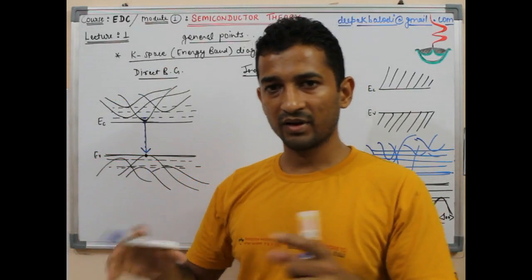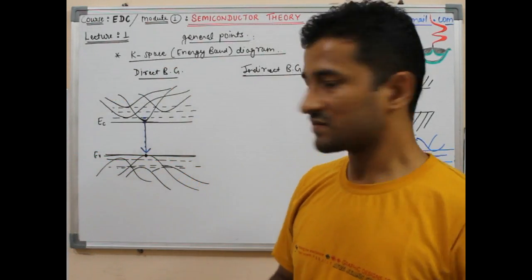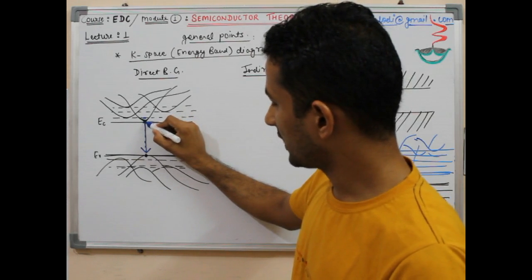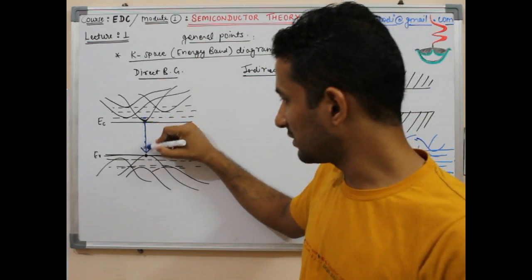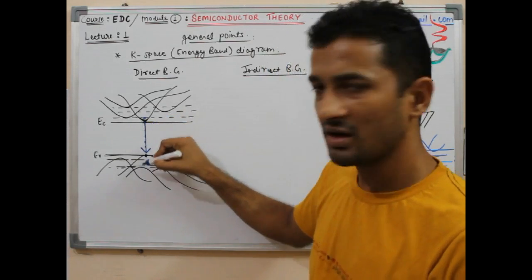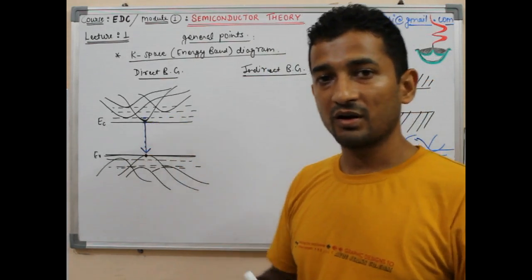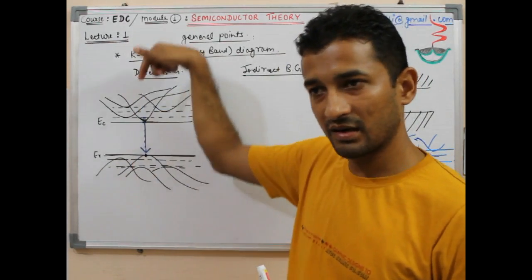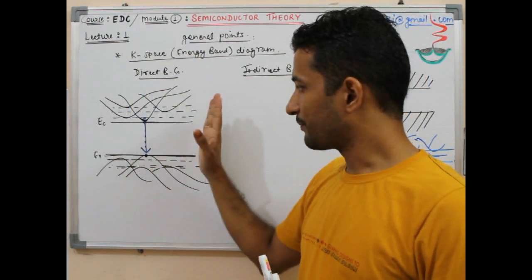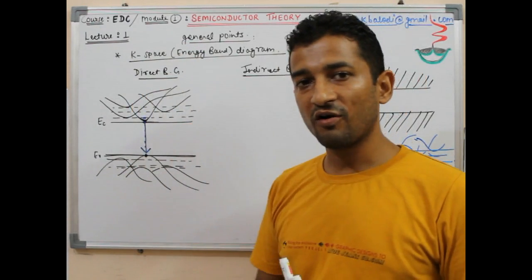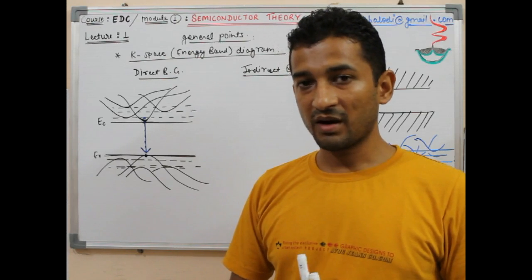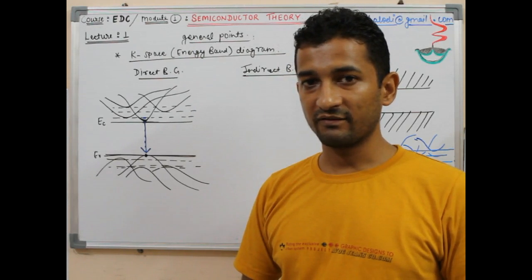That happening in the atomic structure is understood as one electron having moved from the conduction band level to some level in the valence band. But because there is a direct band gap, this process may happen directly, or vertically. There is no alignment of momentum vector required. So please mind, there is no alignment of momentum vector required.